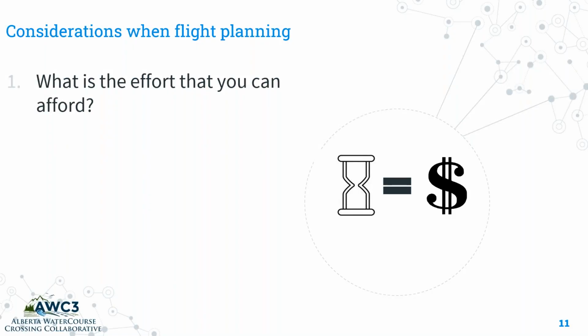So what are some considerations that you need to make with your flight plans? Well, the first should be, what is the amount of effort that you can afford to do for a single flight? And this really ties back to your goals and objectives, which is, how precise do I need my imagery? Do I need 2D imagery, 3D imagery? How many sites am I looking at doing in a day? And as we all know, time is equal to money.